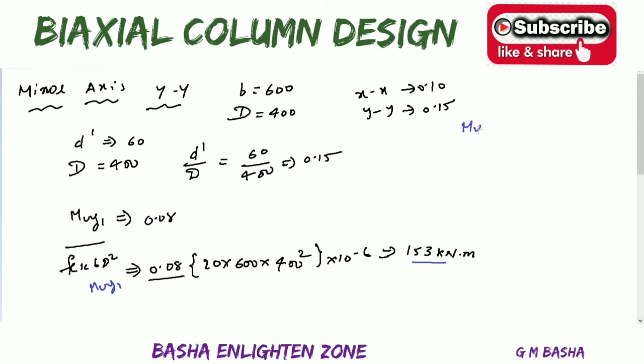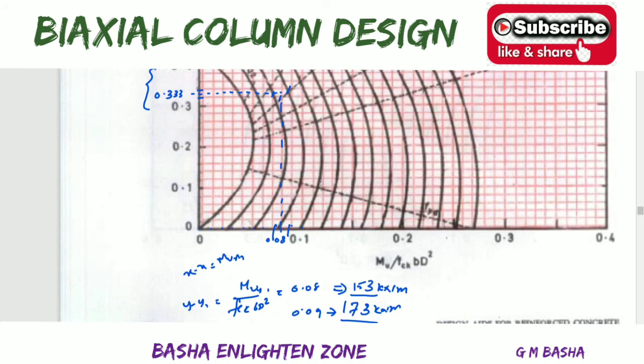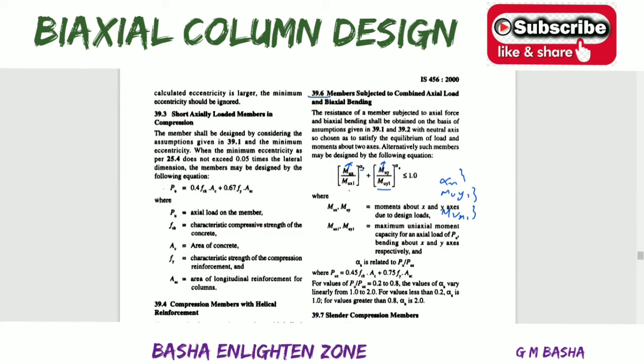So take down some rough data: Mux1 will be equal to how much? That one will be equal to 245 kilonewton meter. Muy1 will be equal to around 153 kilonewton meter. And what about your formula? Your formula will be this one, that is Mux by Mux1. So here we find the Mux1 and Muy1 based on the graph, but there is still one more value pending, that is alpha n.